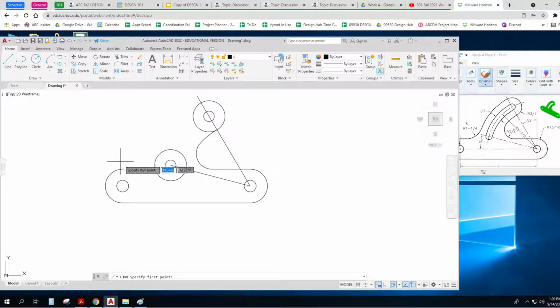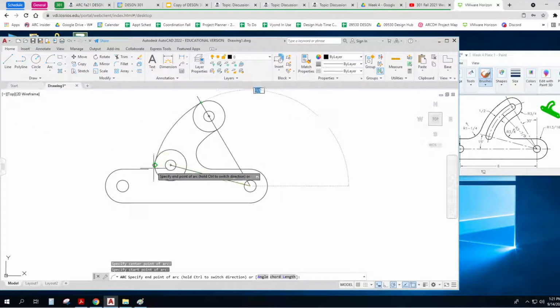Okay, now I know that this line is going to have to be out here again, so I'm just going to draw it somewhere. It got rid of that little line, but I'm going to use that same process of arc because now I know the center, the start of the arc, and it's going to end up down here. Now you should know this is a counterclockwise command. So when I pick my start point, I always want to pick it so that I'm coming counterclockwise.